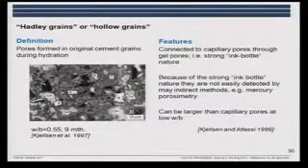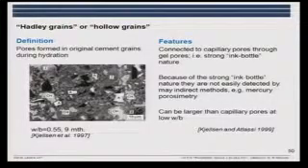You had a cement grain, and the hydration products, you have a small rim here, but otherwise the hydration products have formed outside the initial grain. And here you have a so-called Hadley grain where you have porosity which is almost not connected to the remaining porosity. It's connected through the CSH. So if you have material going through the sample, it will not easily go through this part of the porosity.